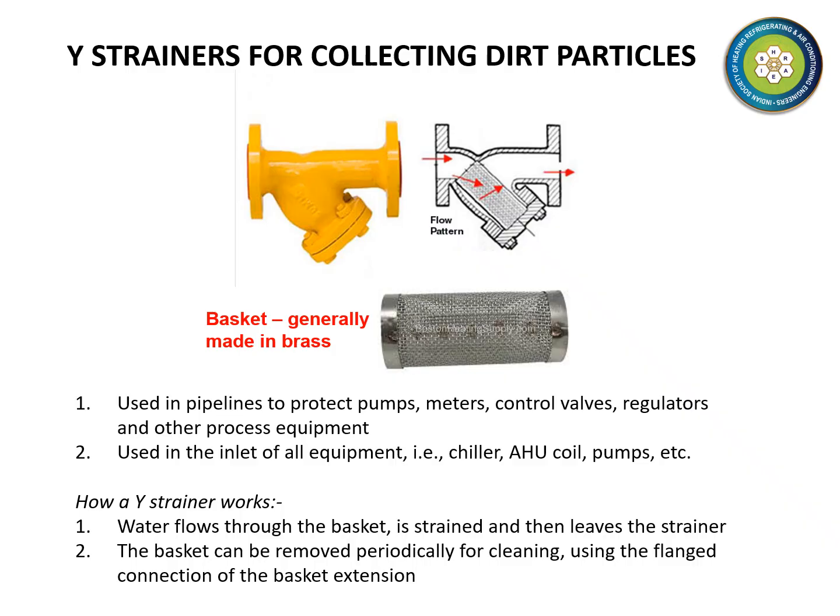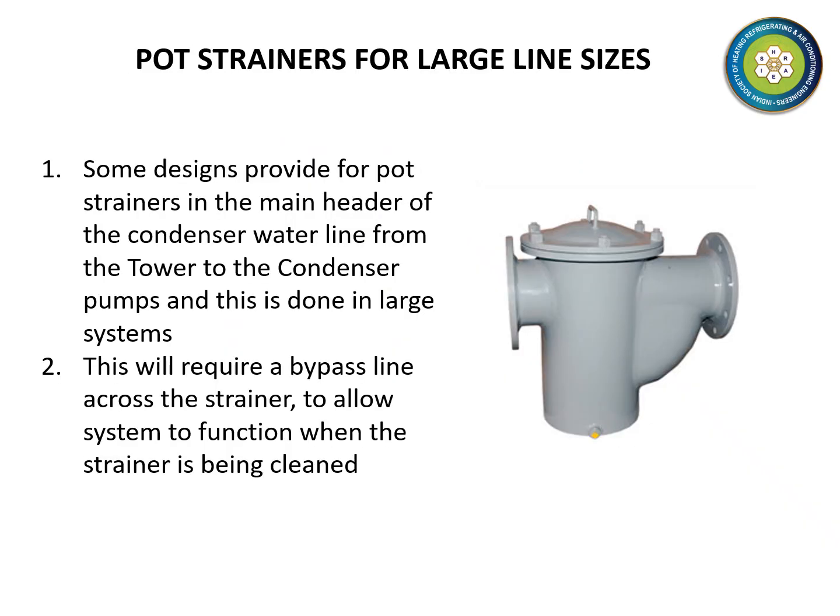Y strainers are used to collect dust particles that might have crept into the water. Dust particles can damage the various components such as pumps, valves, meters, etc. Y strainers must be inserted at the inlet of all equipment, for example, chillers, AHU coils, etc. In large designs, pot strainers rather than Y strainers are used.